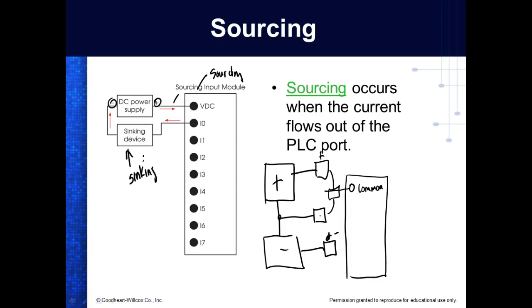Or if you take a sourcing sensor and hook it up to a sourcing input. So if your inputs are sourcing, then with your sensor, you've got to buy what? Sinking sensors. And odds are the company makes them in both versions, right? You understand? So you've got something that's broke, and you buy the first one you see, and you buy the wrong one. You pay $200 for the dang thing, and then it comes in and it doesn't work.